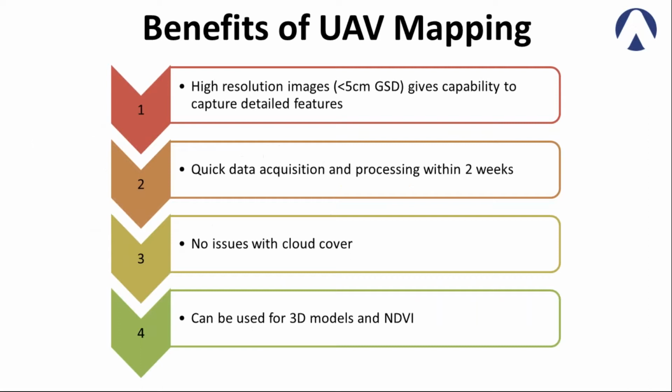Benefits of UAV mapping: high resolution images with less than 5 centimeter accuracy, giving the capability to capture detailed features, quick data acquisition and processing within 2 weeks, no issues with cloud cover, and the data can be used for 3D models and NDVI.